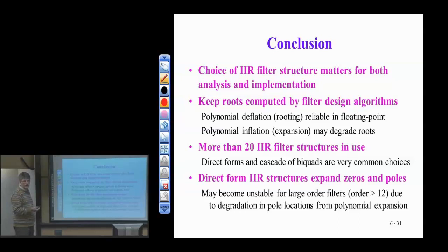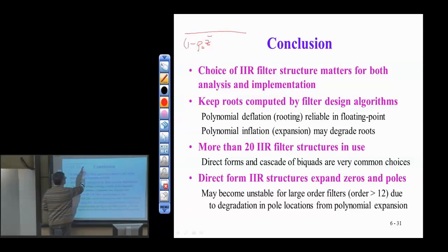The order matters, and even with the best order, you're going to lose something, because every time that we expand, we lose something in floating point. So if I take the biquad case, which I've worked a few times before, 2 poles, 2 zeros. I'll leave the gain off for now.